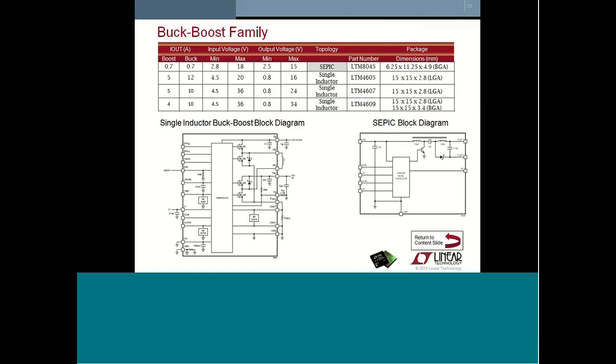On the buck-boost family of micromodules, the choke is external because it depends on our input and output voltages, and also the current flowing through it. We should consider the saturation of the choke and make sure that the one we have chosen is the right one.